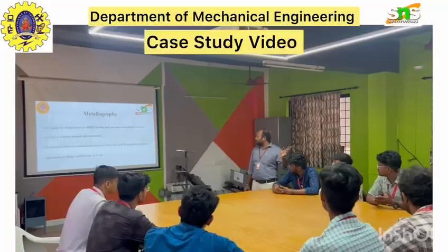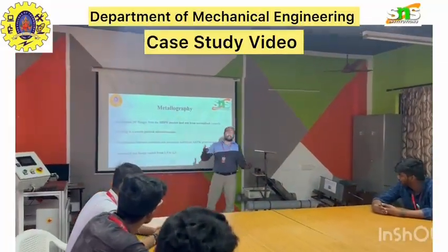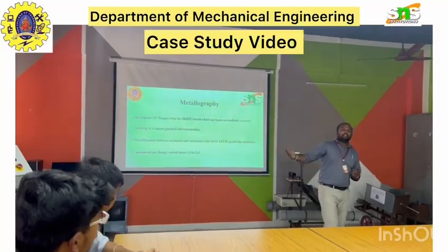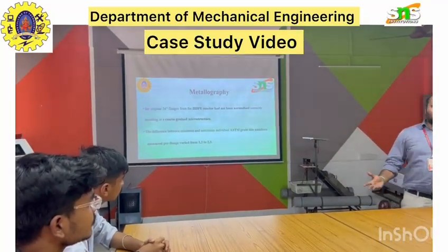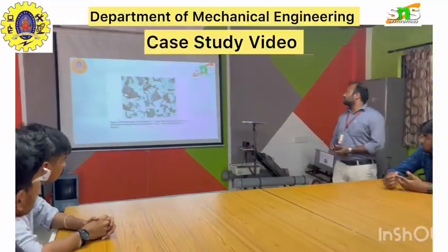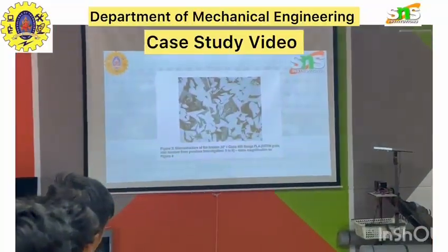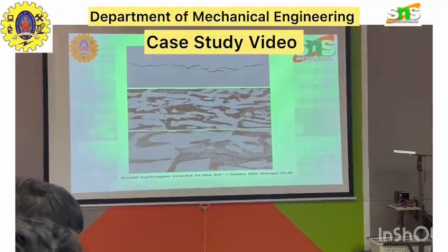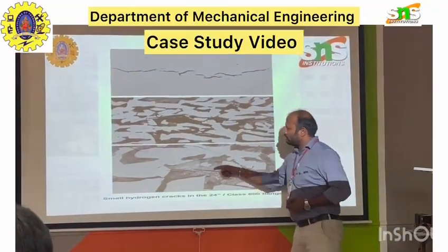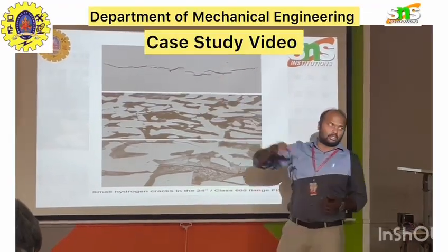As we said, this is a coarse grain structure. When compared with a fine grained material, a coarse grain material has lesser strength, so it can be broken. Next. This is the coarse grain structure of the flange that has cracked. Okay, next. This is an exact view. You can see the crack moving out. We have removed it to see what the cracks are.